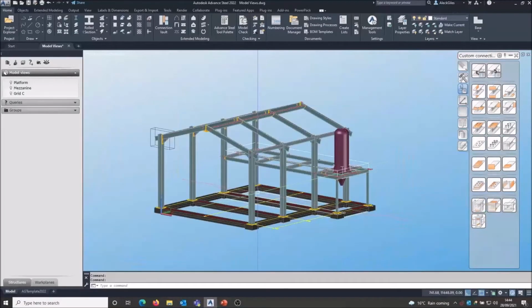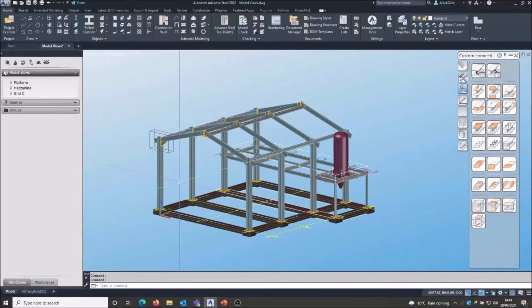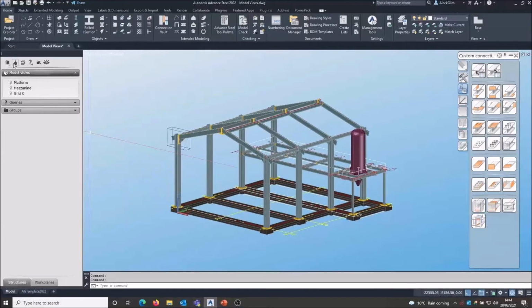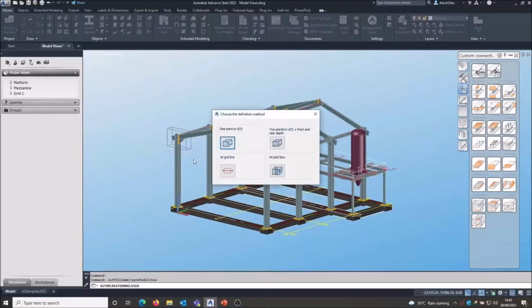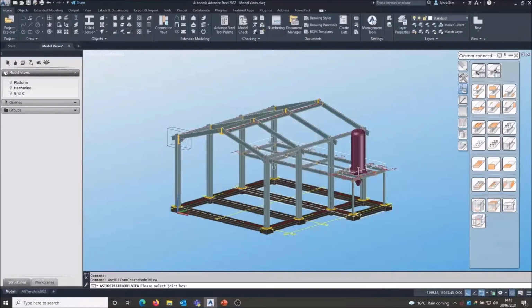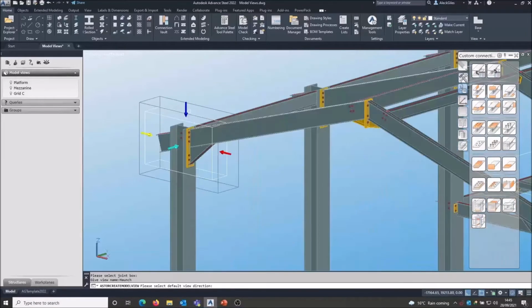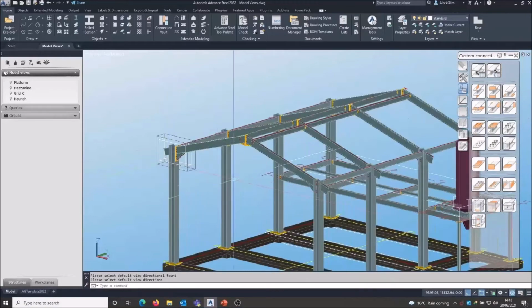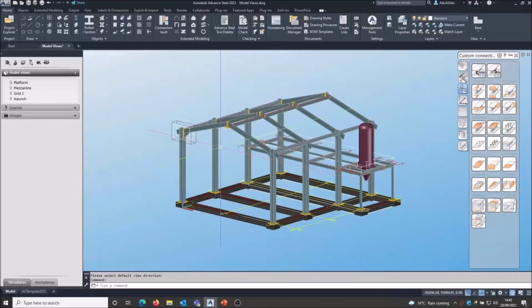And the last type of model view you can create would be at a joint box. Here we go, there's the button, so I'm going to pick that. Here's a joint box showing for that haunch joint, so I pick that box, give it a name, haunch will go. And again, you can see the arrows on each side of that box. So it's drawn in the white box, and I'm going to pick the blue one there. And there you go, I've defined the 4 different types of model view.